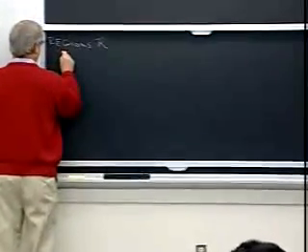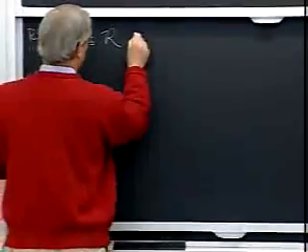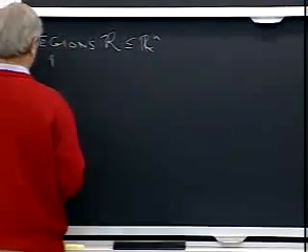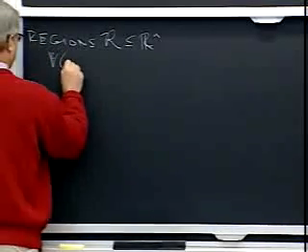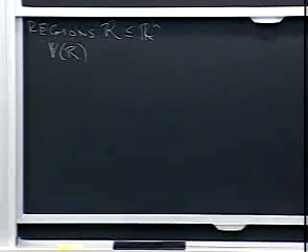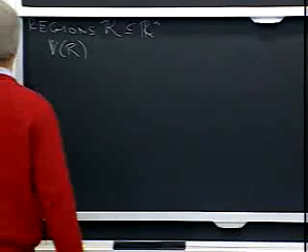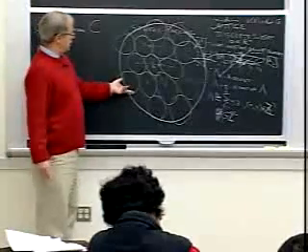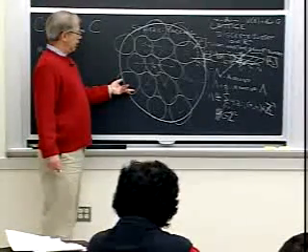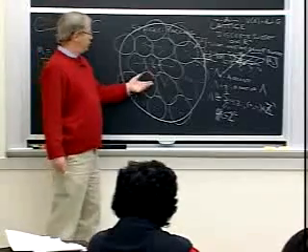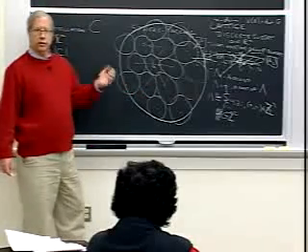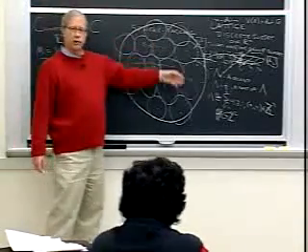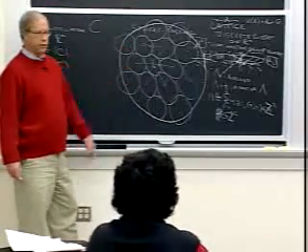I'm thinking of a compact region in an n-dimensional space. So again, let me fix the dimension to n, and we're going to have a certain volume. That's obviously an important characteristic of a region, and I'm going to assume this is finite. And what's the other thing that we basically want? Well, when I pick a constellation like this by intersecting a lattice with a region, eventually I'm going to let the points in this constellation be equiprobable, as I always do in digital communications. 16 points, say they all have probability 1/16, the uniform probability over the discrete points.